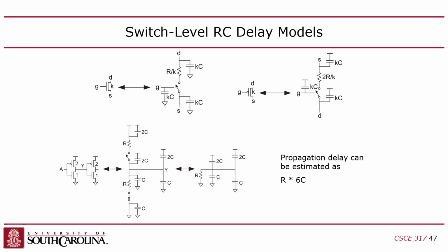But if you simplify your model for this, you're going to associate a resistance value for your transistors. It's just an estimation, though, because remember, if you're in saturation mode, there's no resistance. You just get a constant amount of current. If you're in linear mode, there's kind of a resistance, because it's kind of linear, right? But this is just a simplified model where I associate an R value with my transistor. You guys with me? Okay, all right.